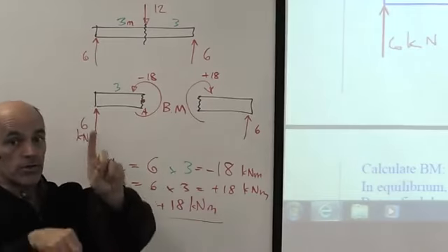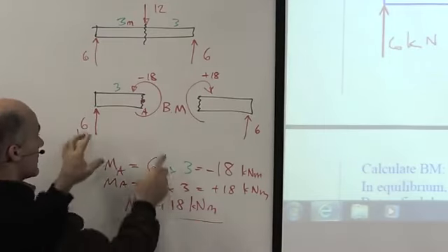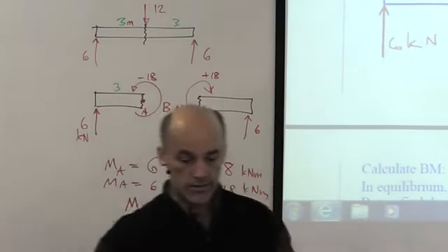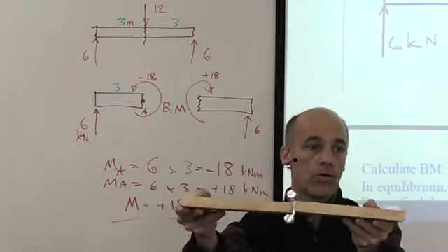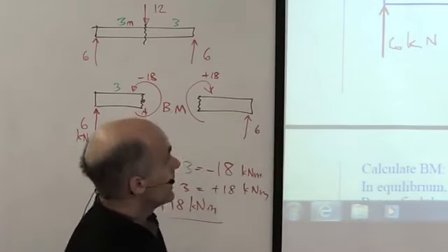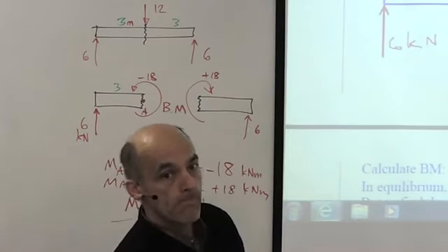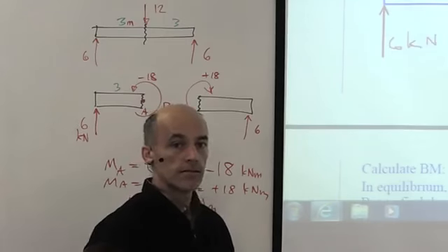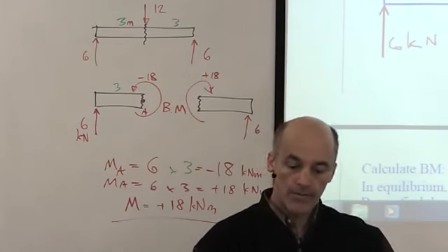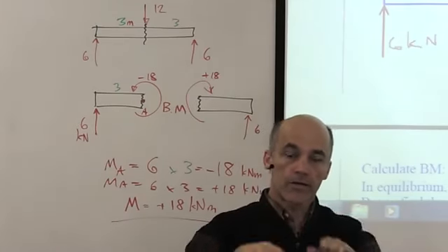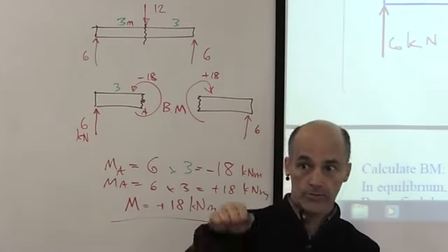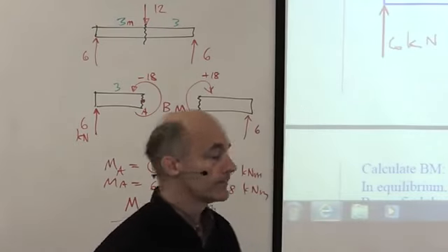So we decide tension and compression by whether they're pulling or pushing. Well, we decide positive or negative bending moment because we will always have a plus and a minus, so we have to decide by sagging or hogging. That's the only option. Like semi-trailers, just tabletop semi-trailers, they build them with a positive bow, they call it, because when they load it up, they come down. Yep, and bridges too. They build a bridge with a slight positive bow because the concrete begins to creep and begins to flatten out. If they build it dead straight, 10 years later people say, oh, that's sagging, I'm not going on there. That's unusual.